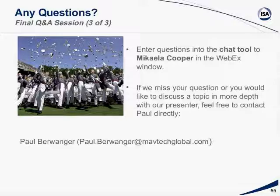Okay, great. The next question is, what is your experience about having different audible alarms? Is it really useful, or is the visual identification enough? Typically, my experience has been the visual identification is enough. You certainly want the highest priority to have a very unique and kind of loud sound, so if the operator is not in front of the console at any given time, it immediately gets their attention. The lower priority ones could be much more subdued. But really, if you're sitting in front of the screen, it's the visualization that's the most important.